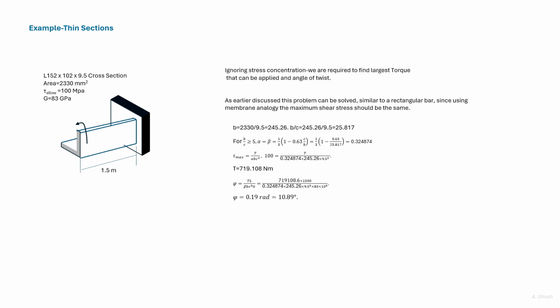Here we deal with thin sections. Earlier, based on membrane analogy, we discussed that thin sections can be treated like thin rectangular bars, or bars with thin rectangular sections.